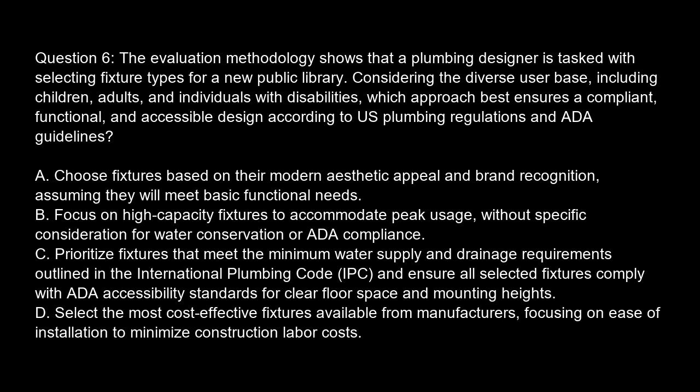Option C. Prioritize fixtures that meet the minimum water supply and drainage requirements outlined in the International Plumbing Code, IPC, and ensure all selected fixtures comply with ADA accessibility standards for clear floor space and mounting heights. Option D. Select the most cost-effective fixtures available from manufacturers, focusing on ease of installation to minimize construction labor costs.